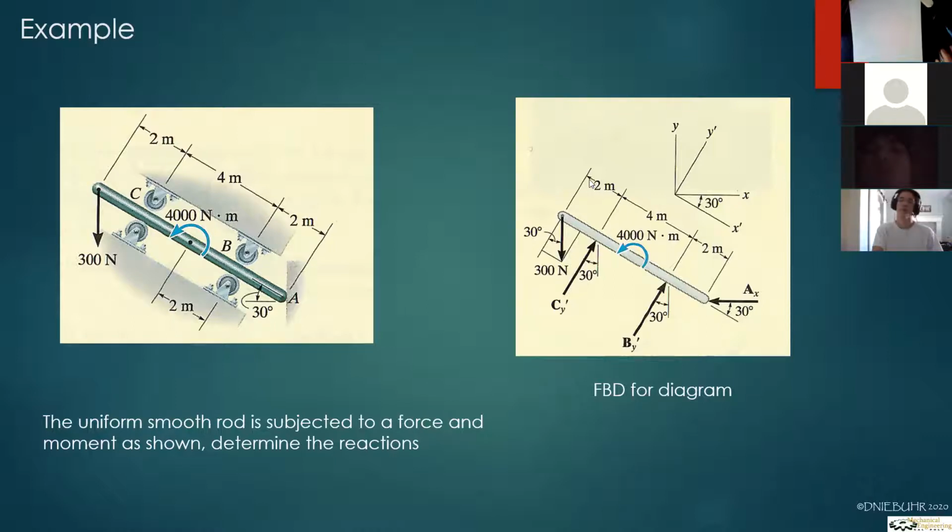Now, whether you get the 2, 4, and 2, that's not critical to your free body. And in fact, if you can put it in and it doesn't make it unreadable, then do it. But a lot of times the dimensions will clutter it up and make it confusing. So I would say the main thing is just to get the forces. That's critical to it. If you can get the dimensions, that's okay, but it's not required.